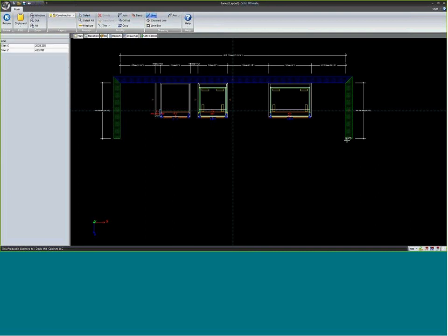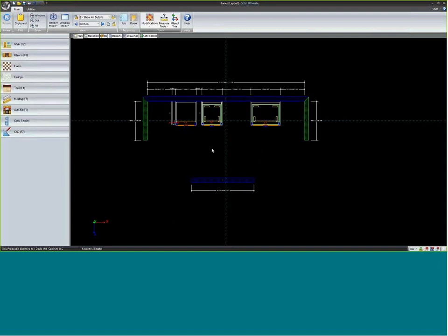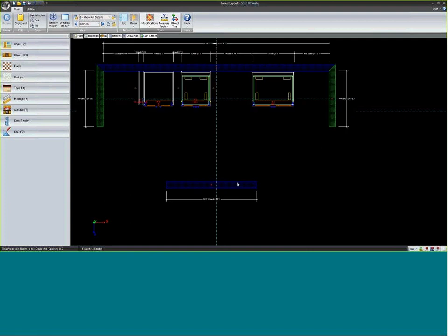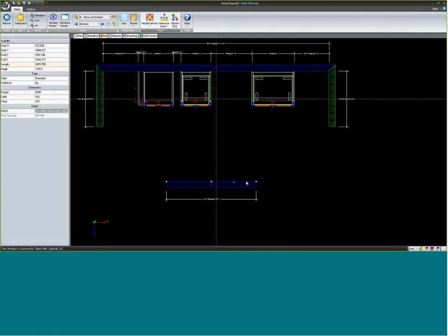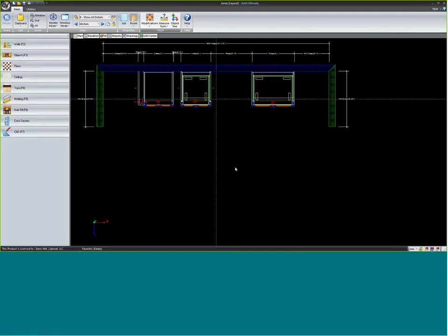These construction lines I think are a better way of, I can position this wherever I want and then go directly over to my wall mode while I'm here and then position an island wall right off of these construction lines. Then when I exit out of wall mode, those construction lines are gone. So snap points are good if you want them to stay around for a while. Construction lines are better if you want to just locate something and then have your wall drawn and then get rid of the lines. The construction lines are a little easier to use.